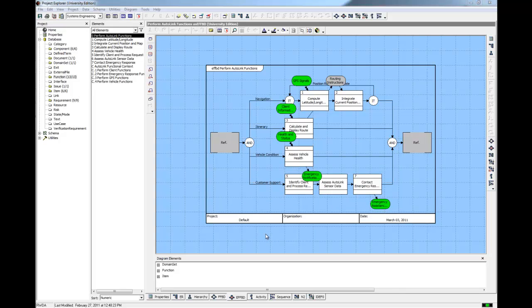Icons on diagrams can be moved within their positioning constraints. To move an icon, first select the object. A move handle appears in the upper left corner of the object. To reposition the selected object, click the mouse within the handle and drag the object to the desired position. Pause the video and take a moment to explore how you can adjust the diagram.